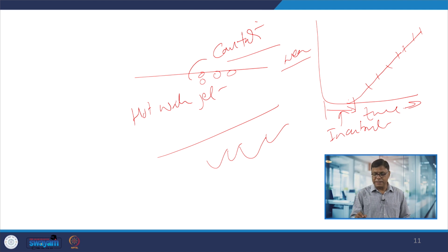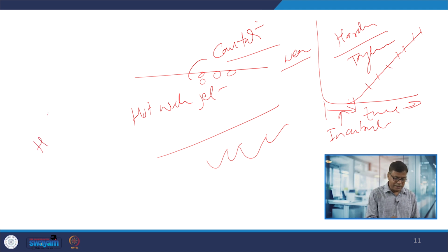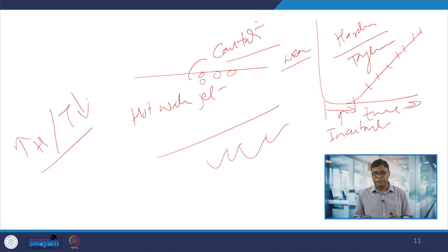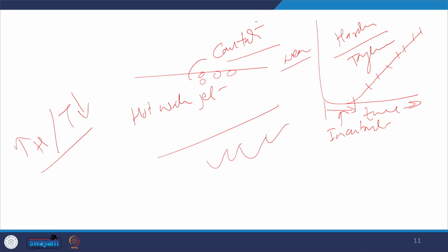What it requires is a good combination of hardness and good ductility, that is, toughness. Okay. So, a very good combination of hardness and toughness is needed, but these two are opposite properties. If your hardness is high, toughness will be low. So, what we do is try to achieve an optimum combination of hardness and toughness through a fine-grained structure and a suitable combination of the various phases.